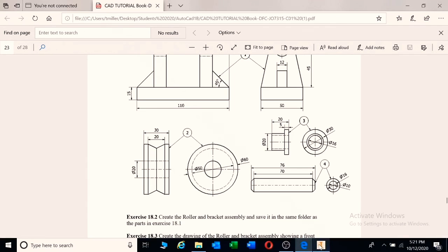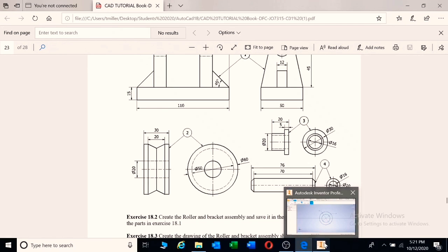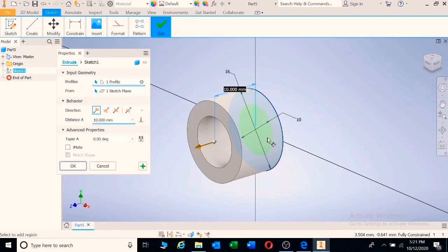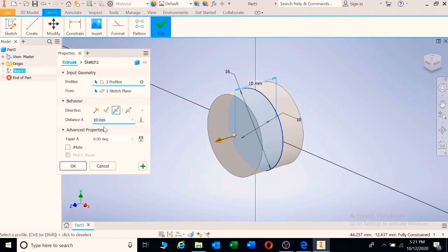Let's go look at our shaft. I'm going to double extrude because it will be symmetrical. I'm going to go out totally 76, and then I'm going to chamfer that by 3 millimeters. So I'm going to say E for extrude, make it totally solid, double. Got a total distance of 70.